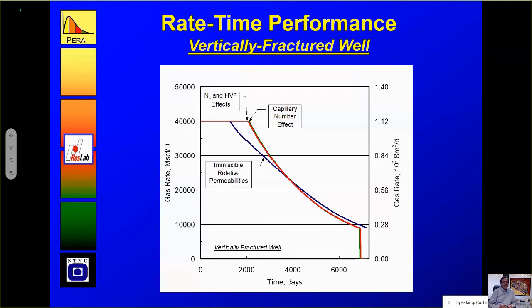Not within the fracture, but on the face orthogonal to the fracture, on the formation which is adjacent to the fracture face. So by reducing the fracture conductivity, you are getting much higher drawdown. This drawdown causes the condensate accumulation on the fracture face. And if the fracture face with the matrix is also damaged, which most of the time is happening due to fracture fluid leak-off, then that's what we saw from the simulation, that you see some effect of condensate.